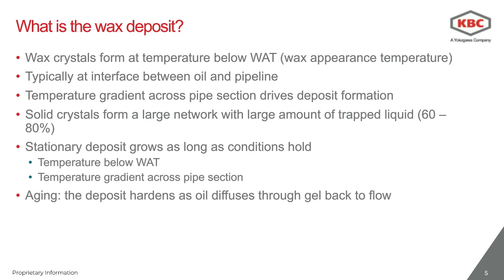When a deposit does form, the deposit is actually a gel. It's formed of a network of crystals connected to each other, with a very high percentage of trapped liquid. So it's a very porous network with a lot of liquid oil trapped in it. The average density of the deposit, therefore, is not very dissimilar from the density of the liquid itself, which is why it's quite difficult to separate from the liquid overall.